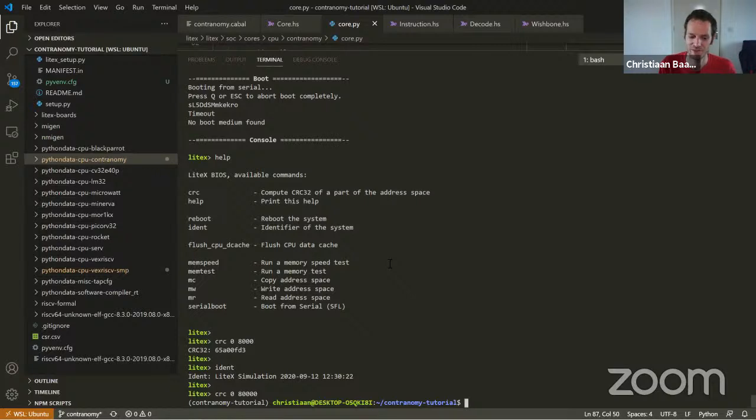But if you have, and you have set it up properly, which is unlikely, then yeah, we should actually now build the entire system on chip, run the FPGA tools, which are going to take our Verilog, the one that we generated from Clash, but also all of the Verilog generated by LiteX for the system on chip, and turn that into an FPGA configuration.